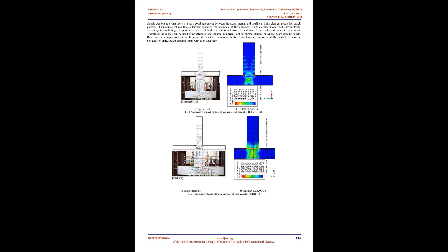However, the CDP model requires the uniaxial tensile strength as an input. Therefore, the relation given in Equation 17, based on the Eurocode 2 [46] recommendation, was used to convert the splitting tensile strength into a uniaxial one.